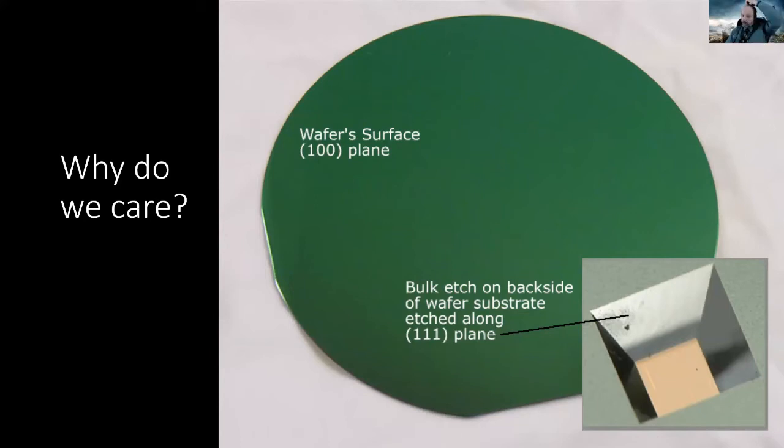This is a wafer that has silicon nitride on it. And then we etched some holes in the silicon nitride, and then subsequently etched the crystalline silicon. So you can etch crystalline silicon with potassium hydroxide, KOH. Sodium hydroxide works as well. That's drain cleaner. You can buy it at Best Buy. So if you put the silicon wafer in a solution of potassium hydroxide, it'll dissolve over time.